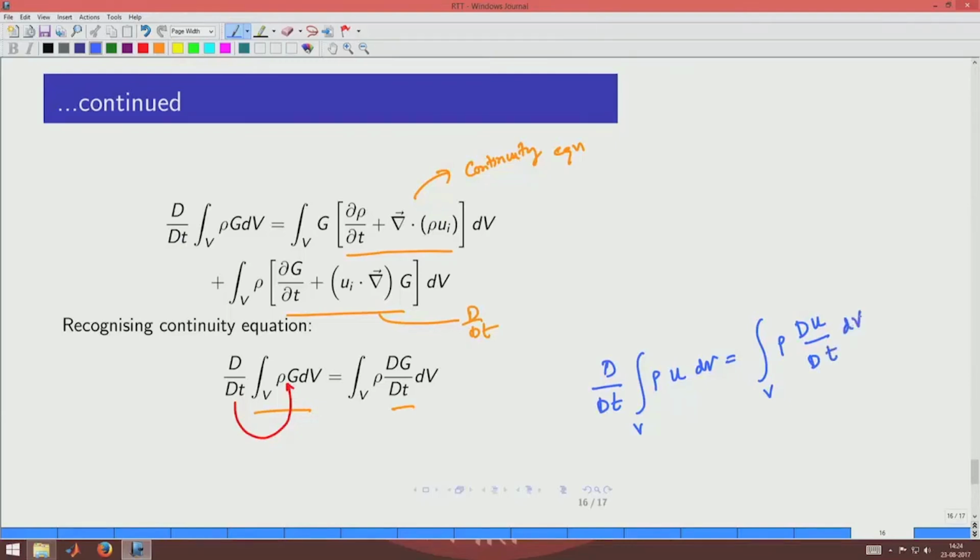And we can also apply this for vectorial quantities because you could do it for each component at a time, and therefore you could also do it in these situations. Okay. So now this is valuable because this is nothing but momentum, and this together gives you the rate of change of momentum, and therefore we can now see that rate of change of momentum can be related to acceleration. So we can see that this term is nothing but acceleration in Eulerian specification.